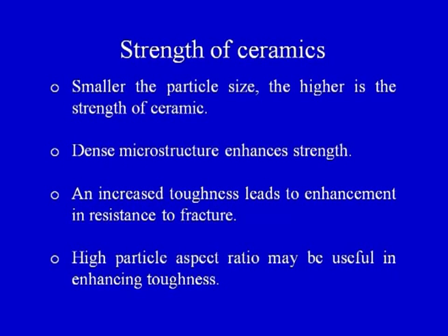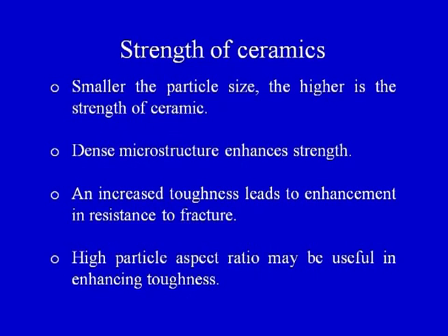Now coming on to the strength of ceramics. Strength is a very common word which has been highlighted here. So strength can be tensile strength, compressive strength, shear strength. The strength of ceramics basically is dependent on particle size: the smaller the particle size, the higher is the strength of the ceramic. Different particles make up the ceramic, because we will see the powder processing technique for processing of ceramics. There we will see how we will blend the powders together to make a ceramic product.